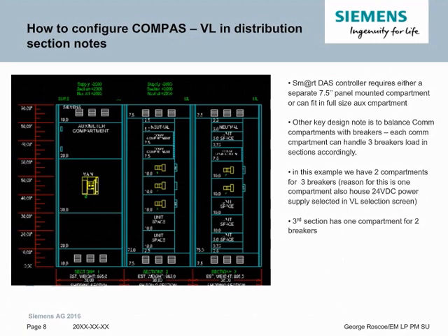And in the third section, since we already have 1 power supply for 7 breakers, that aux compartment has the COM modules and then the lights and switches for those 2 breakers. If you need any additional help with this, please contact your local application engineer or your local business developer. They can help you lay out the board appropriately.